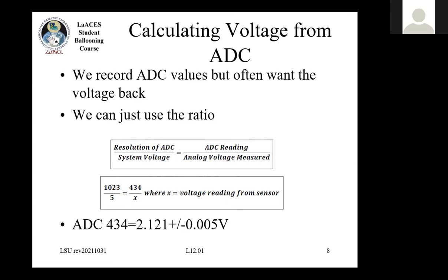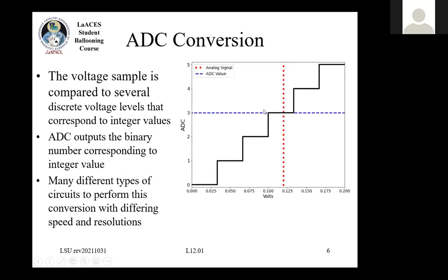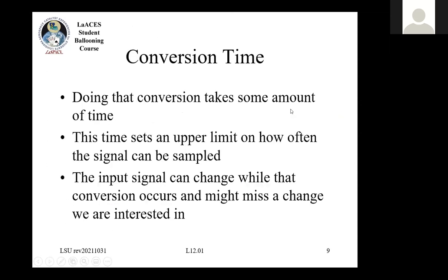So that's why you always want to remember, hey, how wide are these discrete steps? The other important thing, other than the resolution, the other spec that you really care about is how long does it take that conversion to happen, right? So you're going to sample that voltage, you'll do the conversion, and then you'll get the output.